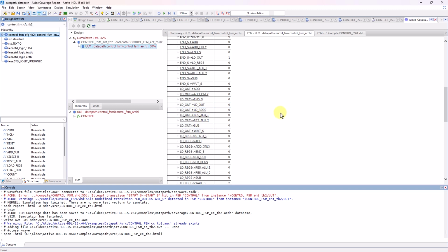And that concludes this video on how to utilize the FSM Testbench Generator along with FSM coverage. The Testbench Generator speeds up the process of testing an FSM, and you could further verify its logic through FSM coverage pragmas embedded into the code. With the variety of strategies and pragmas you can use together, you'll be able to effectively expedite the FSM verification process.